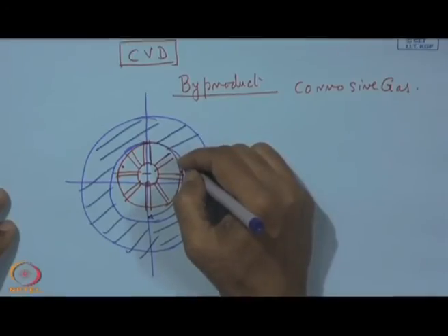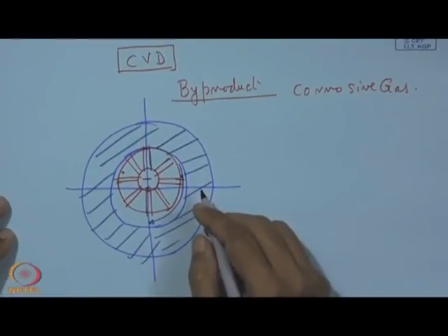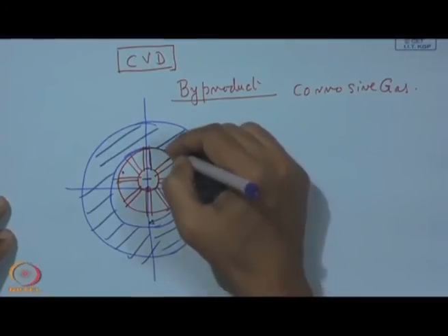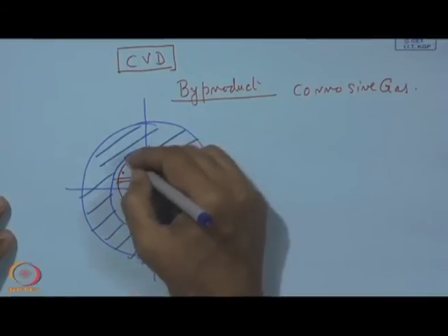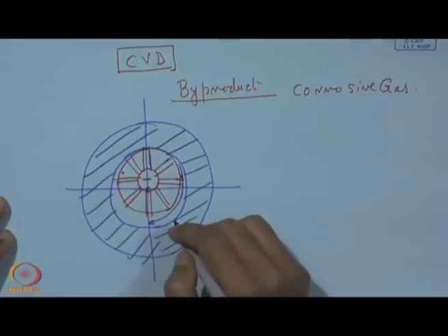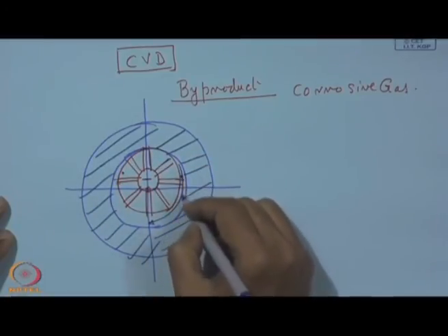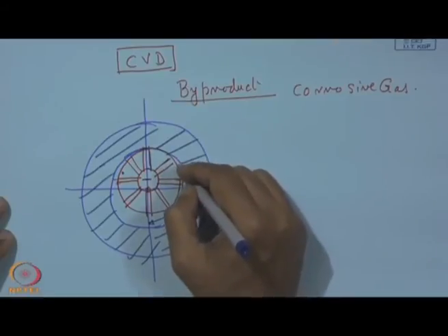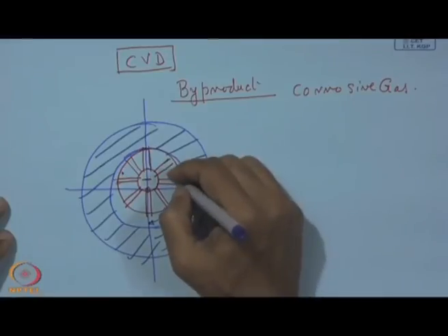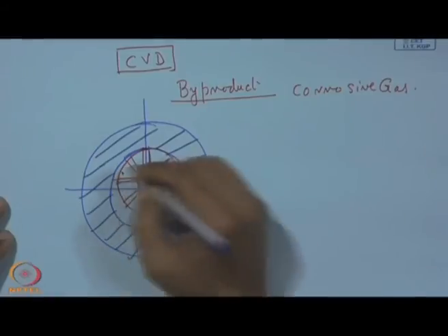So, in principle it is the same practice which is used in a vane pump, only the thing is that instead of a metal casing we have one water ring, and that wall is formed by this ring which is being churned and which is under circulation continuously, and because of this eccentricity we have expansion of this space and then a contraction of this space. So, material will be admitted from this side and then it will be delivered on this side.